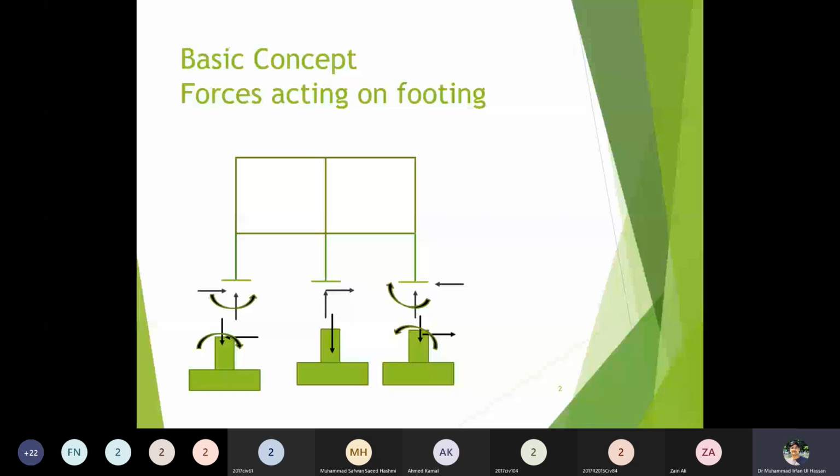That depends on the area of the foundation required, the spacing of the columns, and the load acting on the column, and in that way we can compute the area required for the foundation. But the important thing is where this load comes from. The load comes from the reactions that are developed at the base of the column. Different kinds of reactions are computed, like the reaction due to the service loading and the reaction due to the ultimate loadings. Mainly the vertical reaction plays a key role in computing the area of the foundations. And of course, in addition to the vertical reaction, the moment also plays an important role.